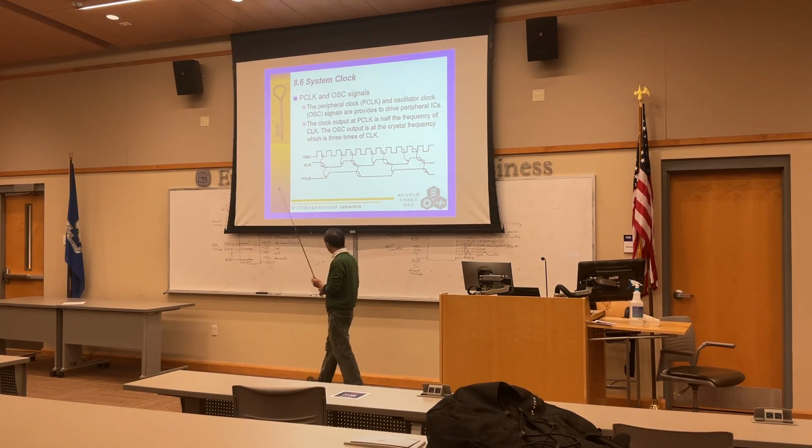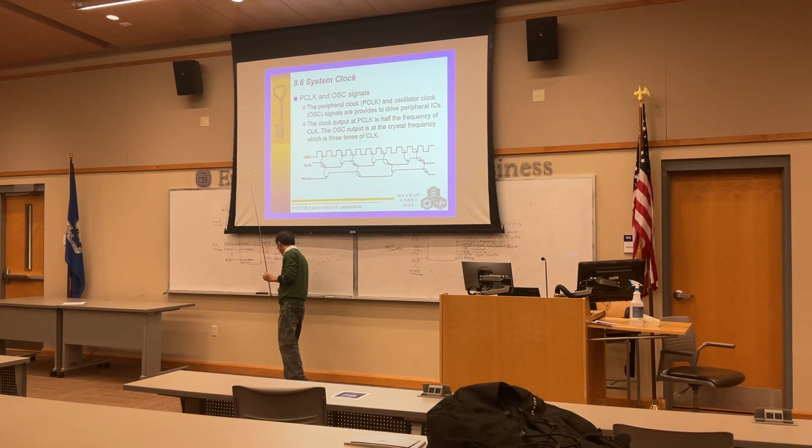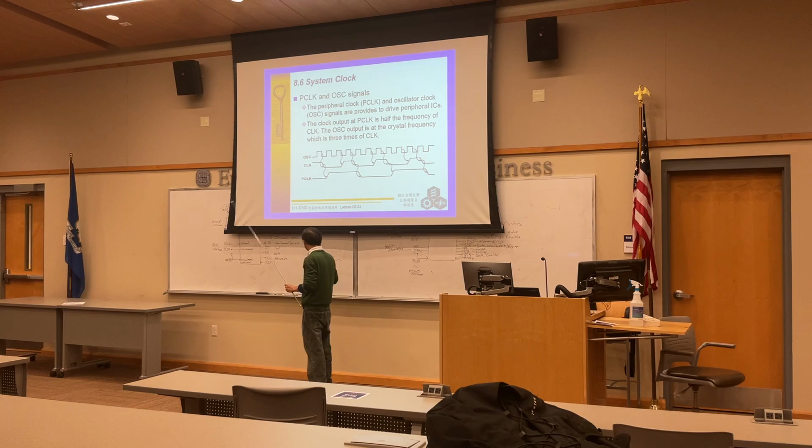And furthermore, the P clock, the peripheral clock, is half of the clock frequency, so the period is 2 times the T clock.